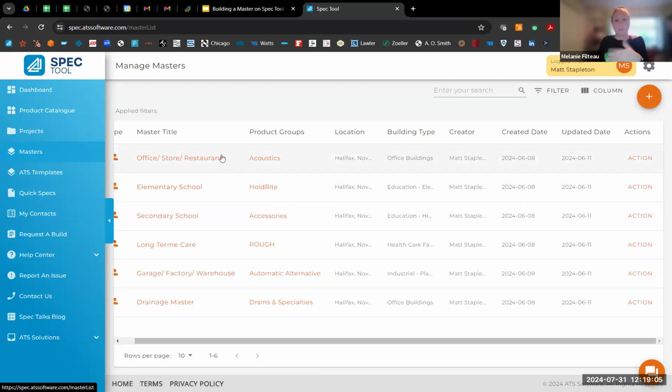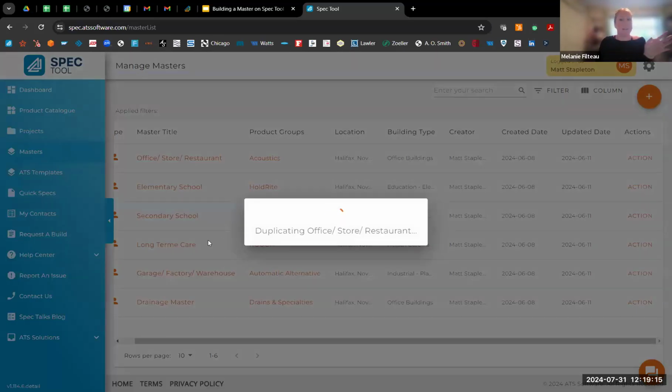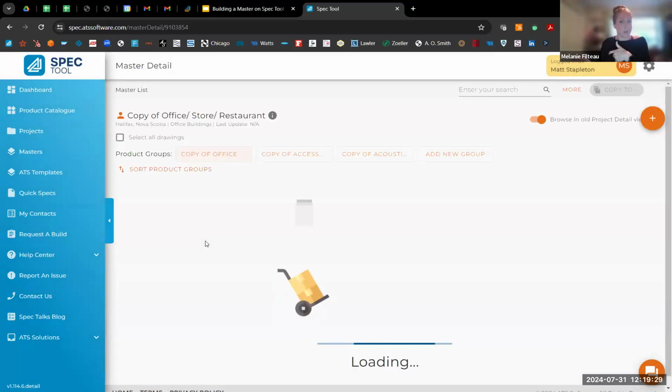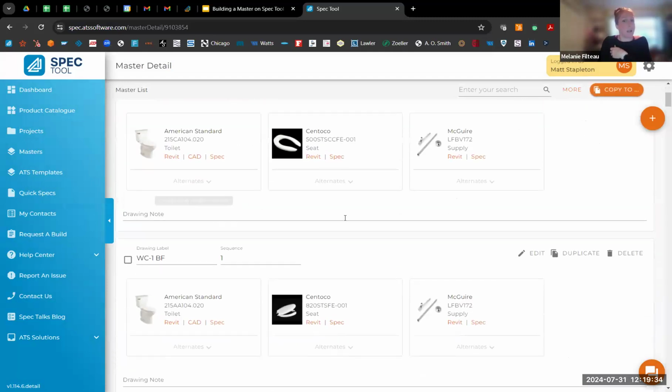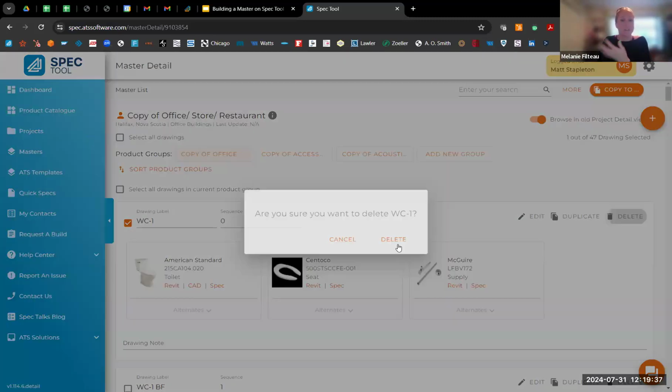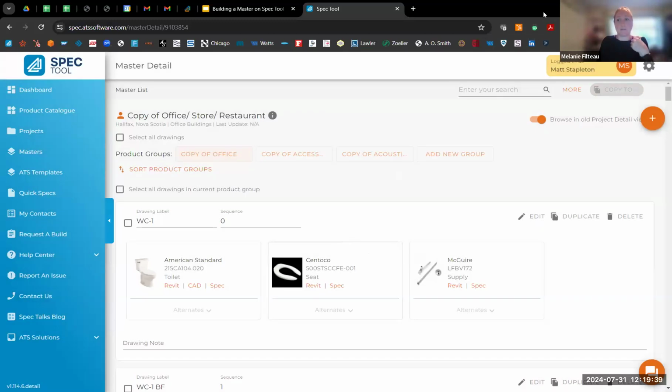So just over here, if you want to do your repeat business, for example, you're working on Subway, you can do a quick action just over here, copy to or duplicate. So you will duplicate your master and you will see everything that you need for a restaurant, and you can change the name. So now your master name will be Subway. And if you want to make some modifications, for example, if the faucet is no sensor, no touch, or if it's manual, you can change it. If you know you don't need a flush tank toilet, you can remove it because now it will be a specific master.